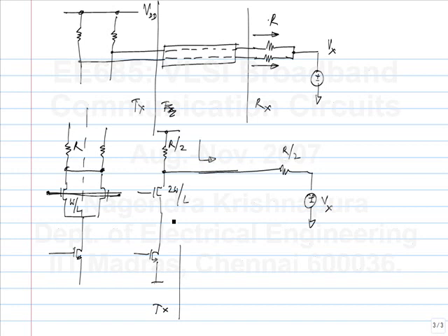Previously I did the analysis assuming that no current was flowing this way, but the common mode voltage at the output of the transmitter very much depends on Vx. So let's say this current is I tail. That represents the total current in the transmitter. If you have an equalizer, you will have multiple differential pairs, and it represents the sum of all of them.